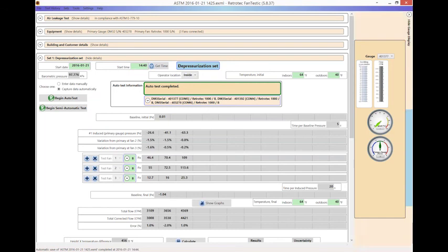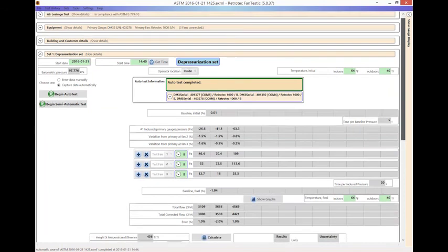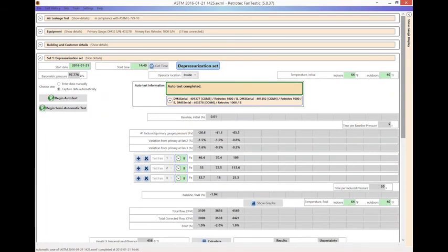Obviously, when you were talking about gauge control, that's only appropriate when you're running more than one fan, which you are, of course. But from testing from high pressure to low pressure, there's a few important things you need to know about that. In the defaults, we put our recommended test pressures and test pressure sequence in there for each standard to give you the maximum chance of passing a test. And the reasons why we go from low to high are many. One is it will achieve 60 pascals faster than it would achieve 10 pascals, so it's faster.